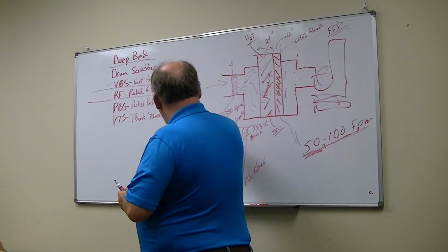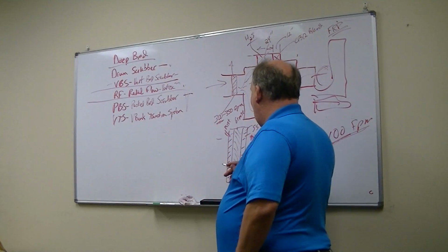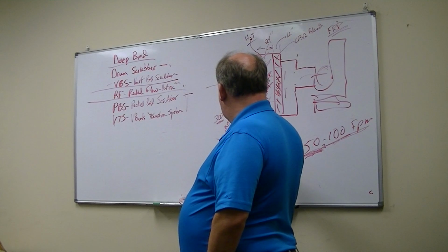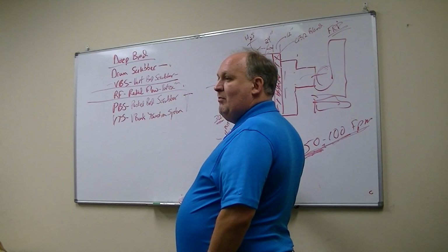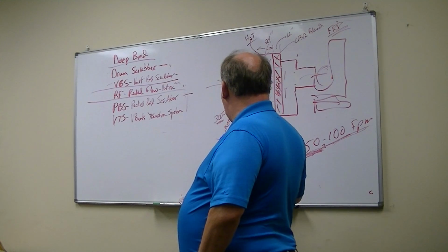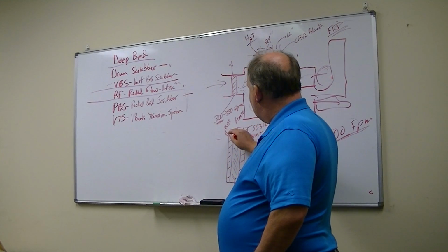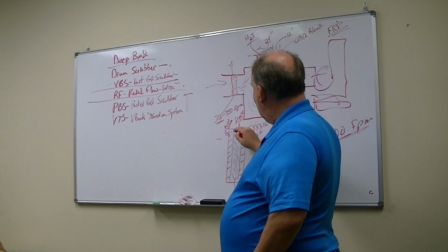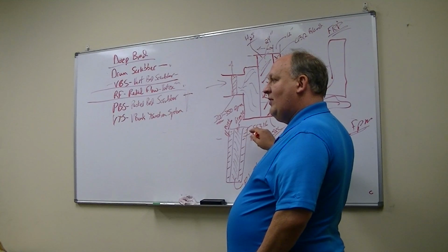Now the grease, on the other hand, doesn't have any problem. The grease is just going to get stuck on these fibers, and so typically you're just using a different mesh which the grease easily bonds to. So can anybody tell me why we have this? If this is being used to collect the mist, and this is being used to collect the grease, why do we have this layer on the back side? Why do we also have a mist filter on the back side of the filter?